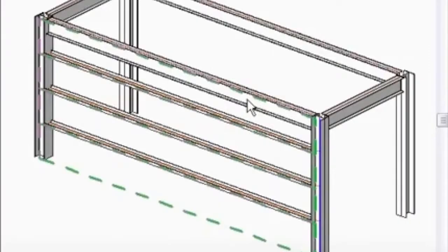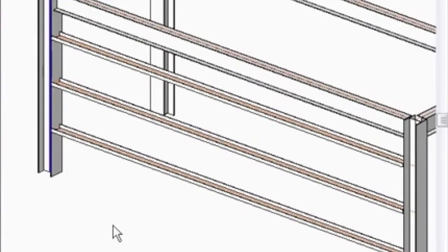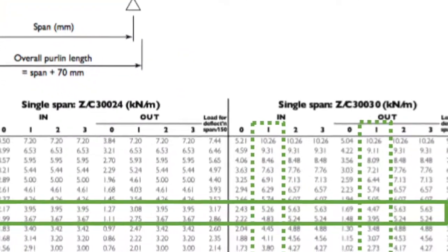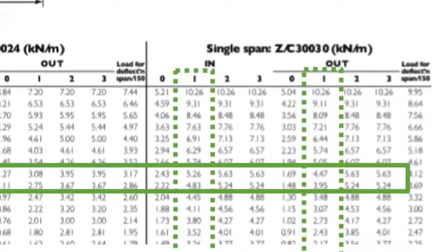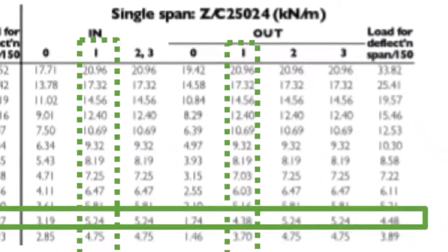We next completed the girt design. This process was similar to that of the purlins, using similar wind load values for both the suction and pressure. An identical process was completed for the north-south elevation, in which a section was suitable. A service limit state check was also conducted and found both sections to be plausible solutions. And that concluded part 1.